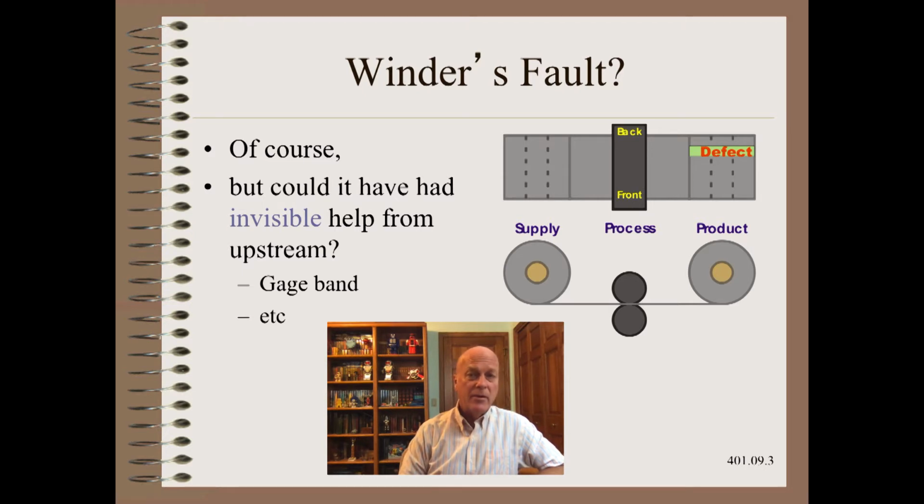Those of you who have been to my Web 101 class will recall that almost all complaints of bagginess on film and metals is simply a gauge profile variation that is excessive. However, even in most other materials, the majority of bagginess is related to thickness profile variations, even if there were also other causes, such as moisture streaks in paper as one example.